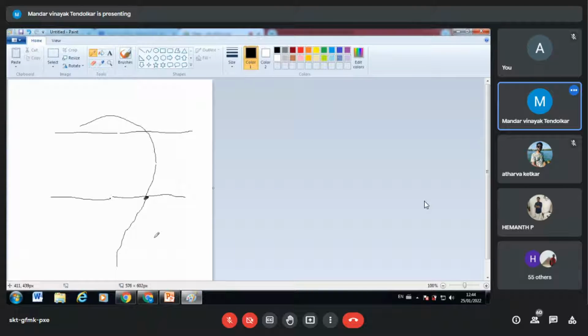Correct? Yes, sir. Now you want to draw an isentropic line, the compression line. So what we have, let's say I will show some enlarged view. One isentropic line like this, and the other isentropic line is having naturally different slope, something like this. Okay. This is whatever isentropic line given on the chart, one line and the second line. Your point is falling in between.